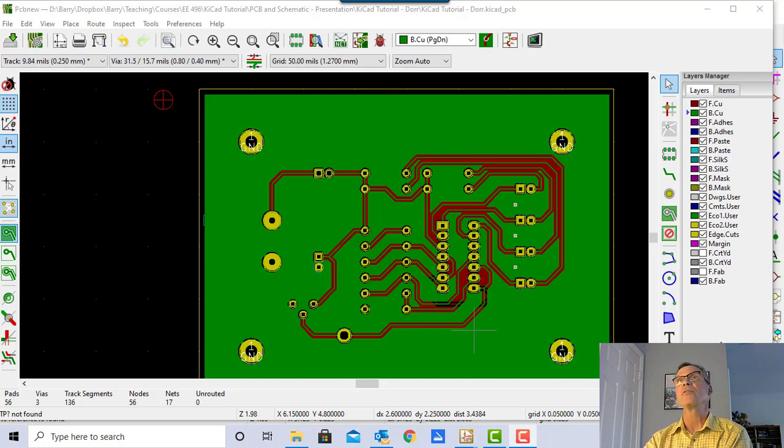We've looked at it on the viewer. It looks really nice. And we've checked it with the design rule checker. Everything's good on the schematic. Everything's good on the board. We had an area where we needed to add a few vias in order to get a nice, good ground plane. And we fixed up our silkscreen. So this board looks like it's pretty good.